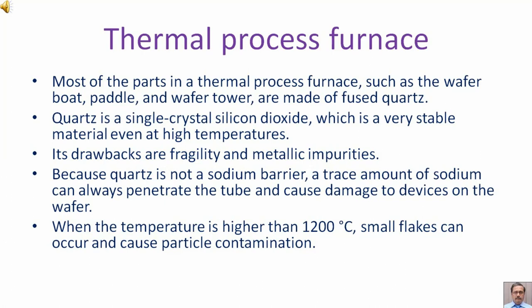Its drawbacks are fragility and metallic impurities. Because quartz is not a sodium barrier, a trace amount of sodium can always penetrate the tube and cause damage to devices on the wafer. When the temperature is higher than 1200 degrees centigrade, small flakes can occur and cause particle contamination.